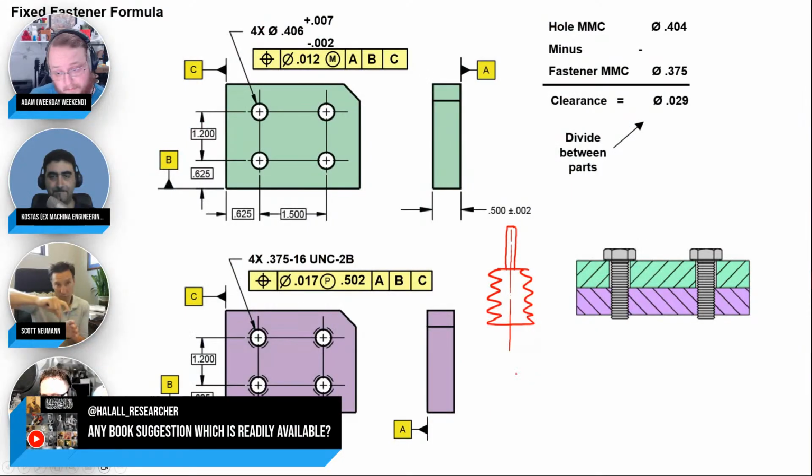But position on threaded holes is hard to measure. Are there any best practices for working with position on threads? Yeah, you probably use thread gauges. Thread gauges are like little things that you can put in there, and then they have a little stalk or diameter that sticks up, and that would be ground on the center of the pitch. And so then you can thread those into the hole, and now you've got this really nice precision diameter you can touch off of.